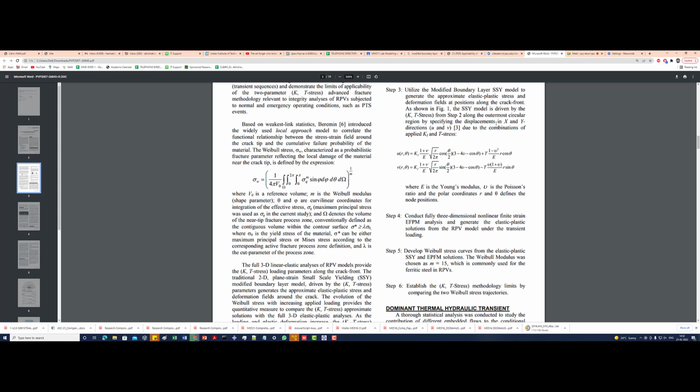So you can calculate the radius of the plastic zone based on your plane stress, plane strain formulation. Safer would be to take the worst case, which will be plane stress. So take 1 by 2 pi, and K1C is 20 divided by 200 whole squared, right? So K1C by sigma not, whole squared. So that becomes 1 by 10, so 1 by 100, so 1 by 200 pi.